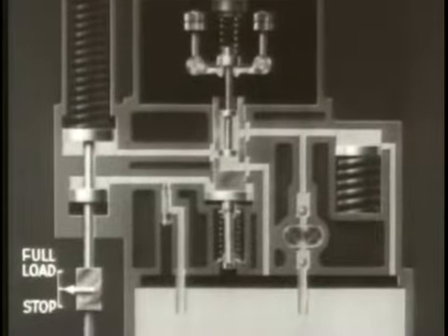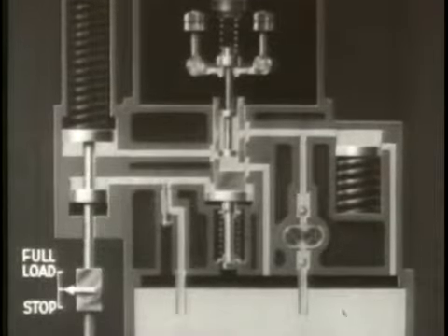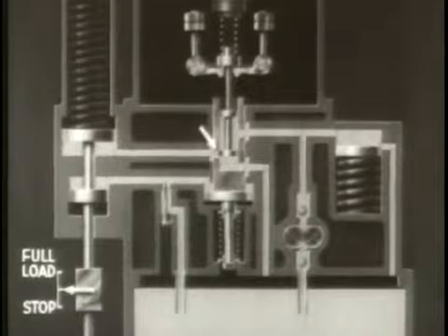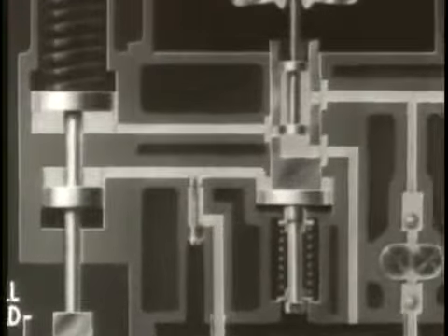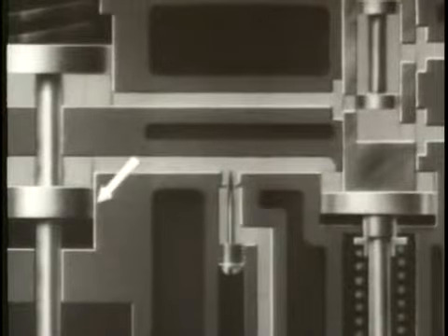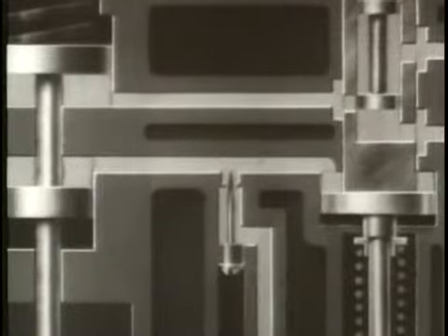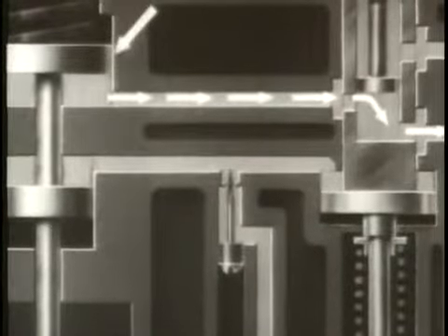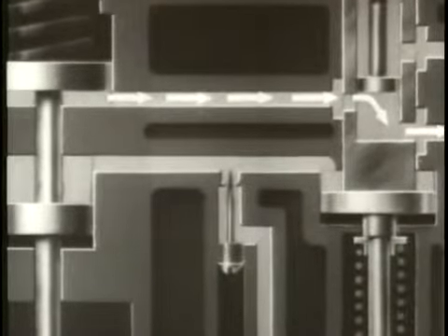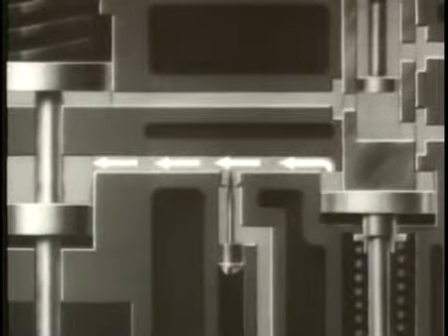To increase the regulating governor's sensitivity and to prevent overcorrection, a compensating mechanism is used. This allows the pilot valve port to remain open just long enough for the engine speed to return to the set rate. A compensating plunger on the power piston shaft moves in a cylinder which is also filled with oil. When the engine speed increases and the power piston moves downward, the compensating plunger is also carried down, drawing oil from a cylinder below the pilot valve bushing.